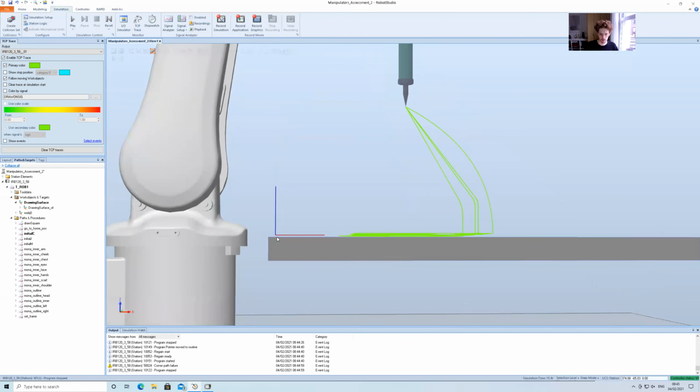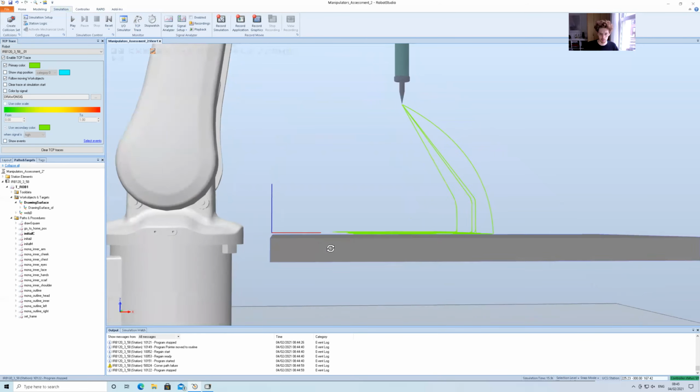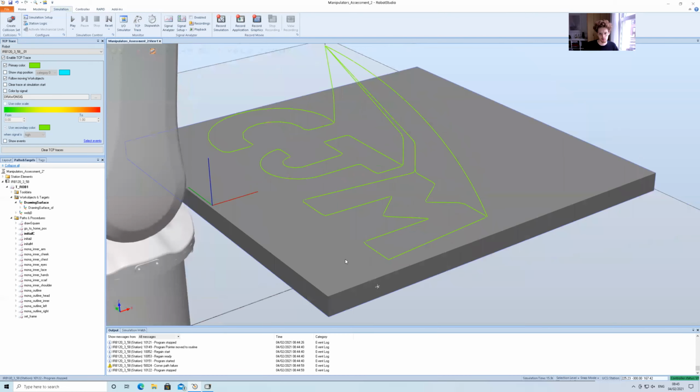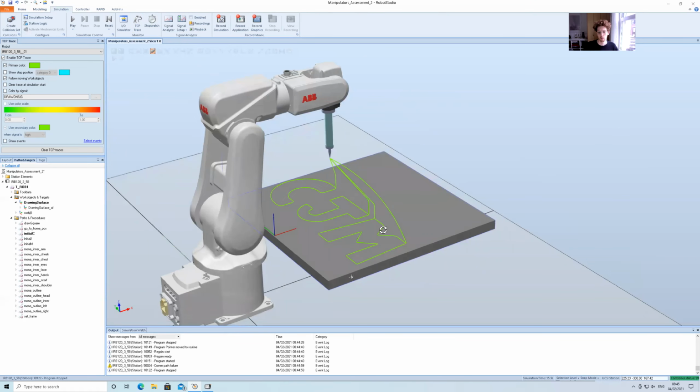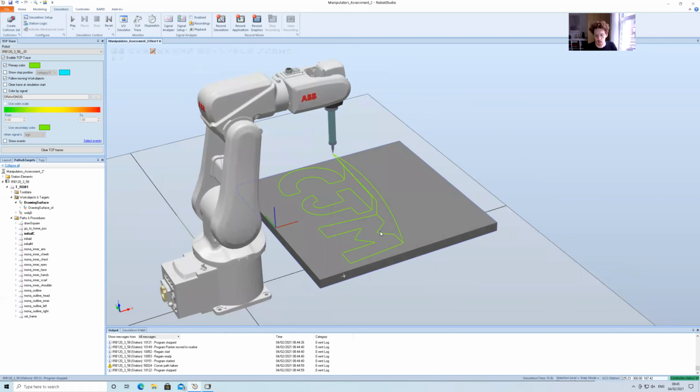That's because I've defined the work object as a couple of millimeters off of the table. So in the scenario where this was actually holding a pen, we wouldn't be slamming into the paper and possibly ripping it to pieces, as that's what this is supposed to simulate, a robot drawing. So I've gone for an art-themed submission with the other 2 programs, both drawing.